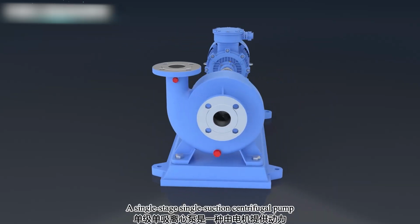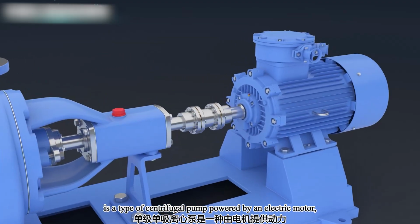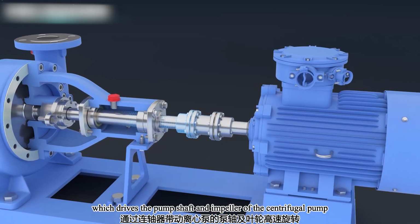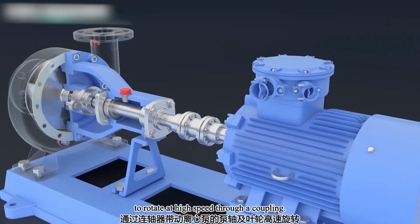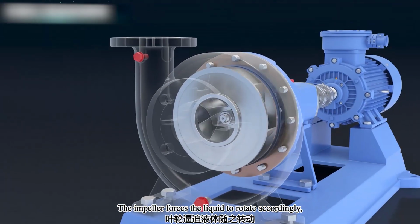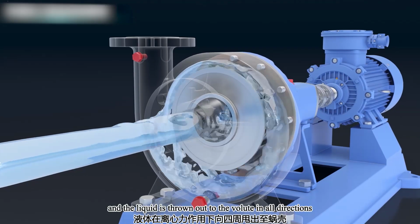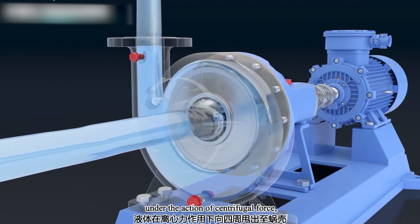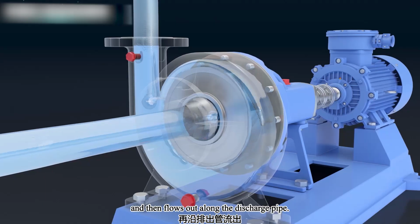A single-stage single-suction centrifugal pump is a type of centrifugal pump powered by an electric motor, which drives the pump shaft and impeller of the centrifugal pump to rotate at high speed through a coupling. The impeller forces the liquid to rotate accordingly, and the liquid is thrown out to the volute in all directions under the action of centrifugal force, and then flows out along the discharge pipe.